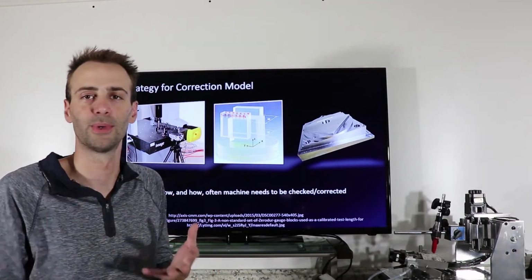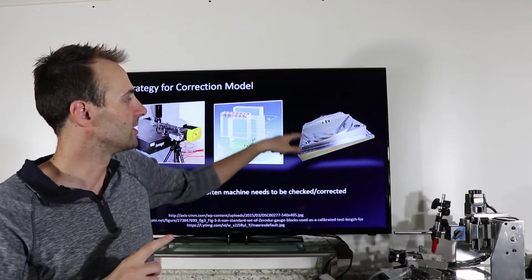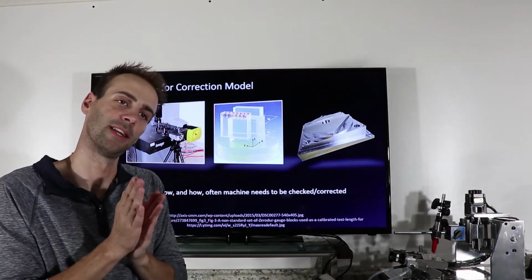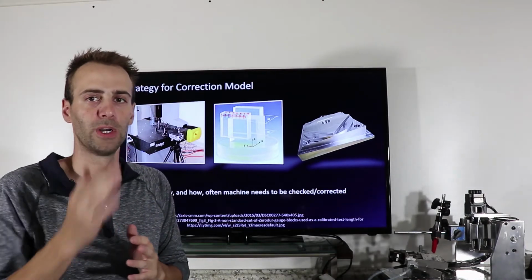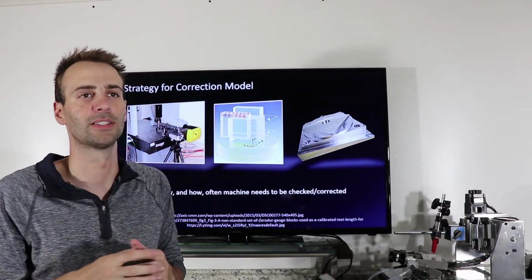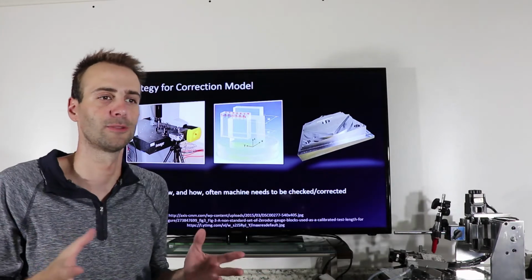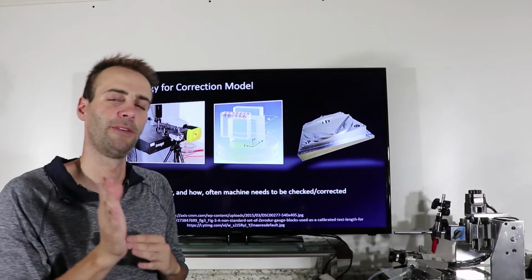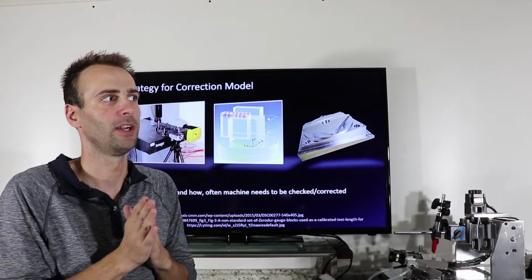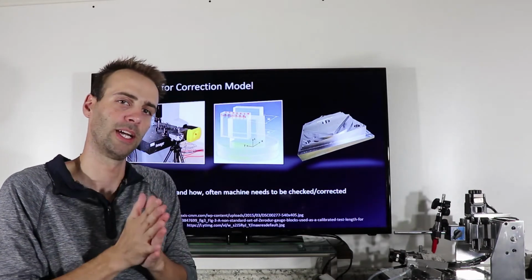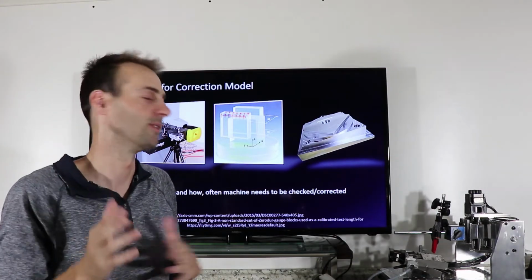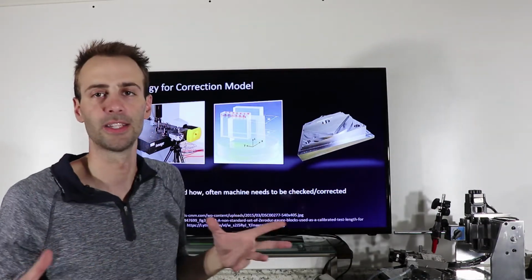So is it circular? What's the surface finish? Is the step height correct? Things like that. And then the diamond up top is a linear coordinated motion move to get your facets on the diamond. And again, that tells me how consistent it is. So a circle tells me how fast I can change, but the diamond tells me how stable that trajectory really is. So the surface finish on the side of that can tell you a lot of things.